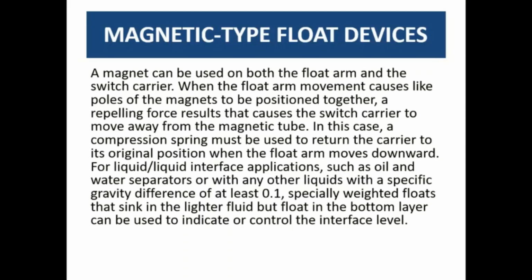I have often seen this type of level device installed in a CSTR, where your final product accumulates in the process area, in any running accumulation tank where you are feeding, or at the bottom part of the distillation unit, because they give a very precise reading.